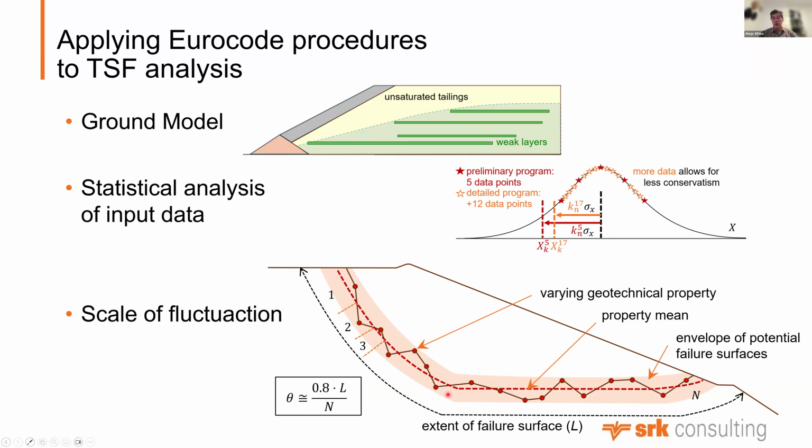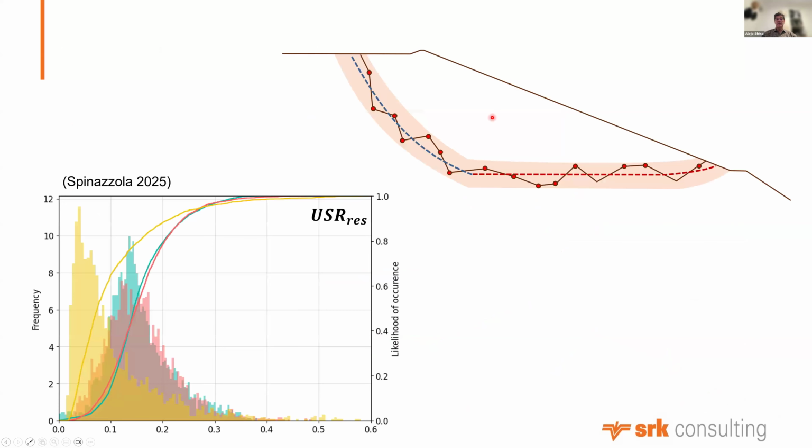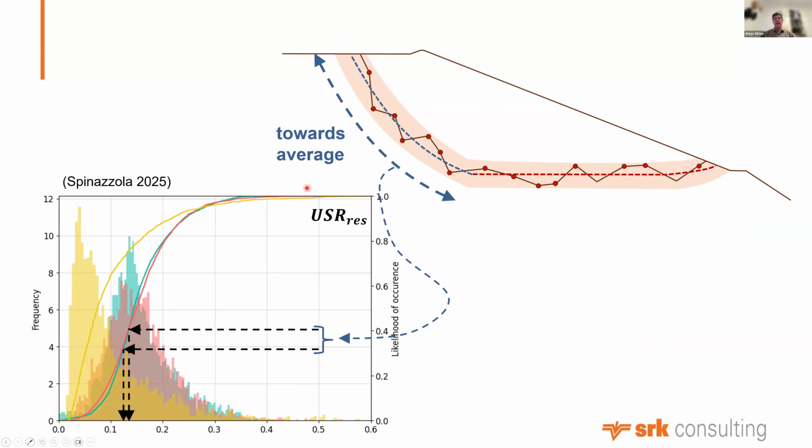So when you go across or when you go along what could be a weak plane, you have to treat those materials differently. So for instance, we have this potential failure surface. This is the range of potential sliding surfaces that we are considering. And here, because you cross a lot of weak layers, you cannot be that unlucky that along this line, everything will be weak.